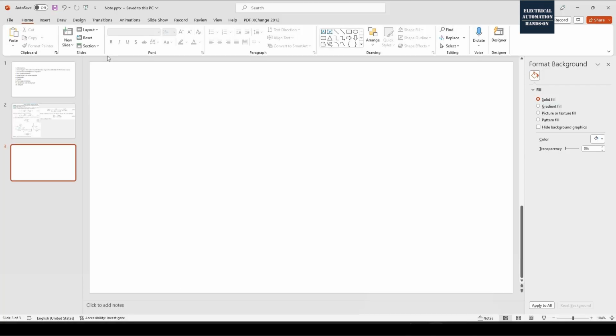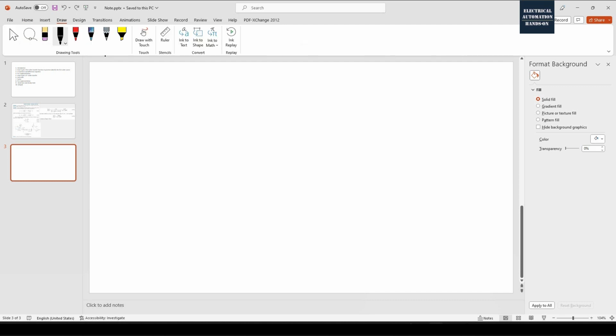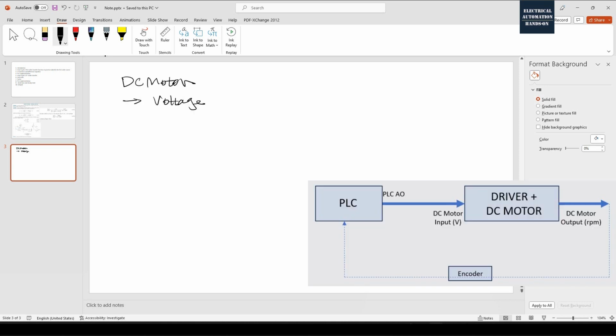Firstly, we need to identify if a first order system can represent your system. The easy way, from my personal experience, is to give the system a step response and watch the system response curve. For example, if we are going to get the transfer function of a DC motor, we know a DC motor can react as a first order system. We can apply a voltage as input, and then monitor its speed. The speed is the motor output, right?